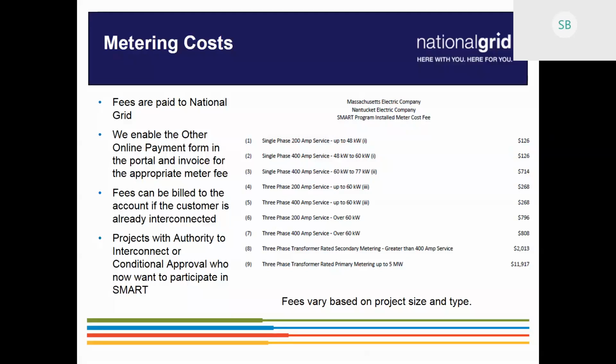So let me just clarify something. Anytime a customer is upgrading an indoor meter, they were required to go outside, and that's been for decades. We've required that under our prior ESBs for metering. We have to remember that DG has a special tariff, a special ESB, but there are plenty of other requirements for services that we've had for decades. Any time a customer with an indoor meter was going to go from a 60 amp to 100 or 200 amp, they were required to put the meter outside. So any service upgrade, which is what you're probably talking about, we should attempt to bring them outside.